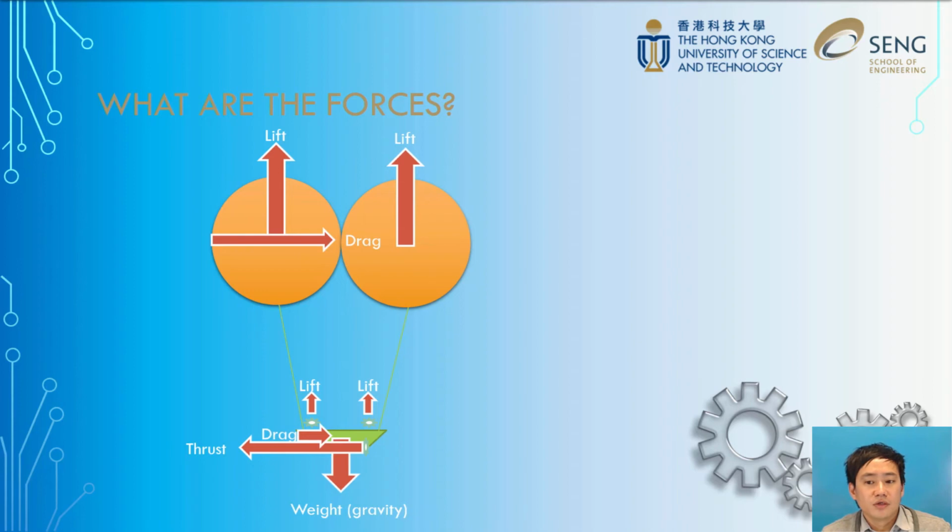In the situation of airship, there are 2 types of forces that you have to pay additional attention to. As the buoyancy force almost balances out the weight of the airship and the projected area is large, the airflow or the air current will play a significant part in the whole journey. So make sure that you pay attention to the external wind force or air current acting on your system. Besides, you're also going to use propellers to generate the thrust for movement, and the torque reaction has to be taken into account in the design process.